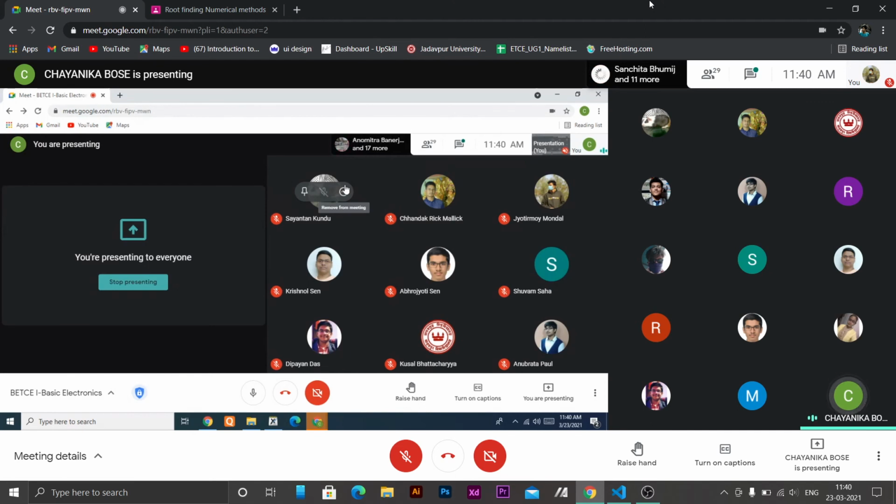Under equilibrium, at the edge of the depletion region, there is the equilibrium minority carrier concentration. So if I ignore that, injected carriers must not be there. So when the signal abruptly changes from plus V to minus V, during the plus V state carriers were injected. Now corresponding to this minus V voltage, the minority carriers should not be present there.